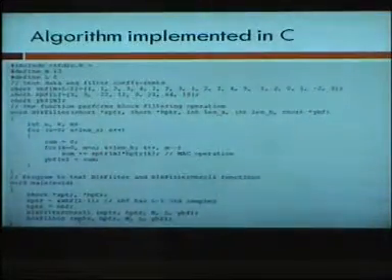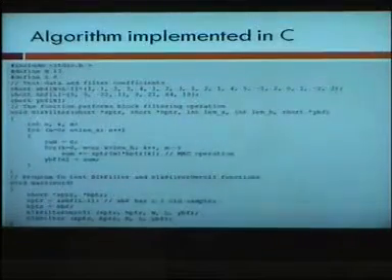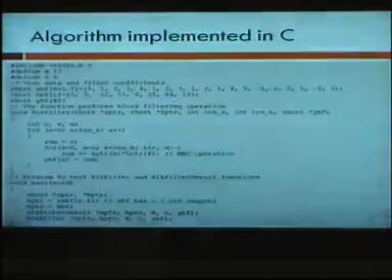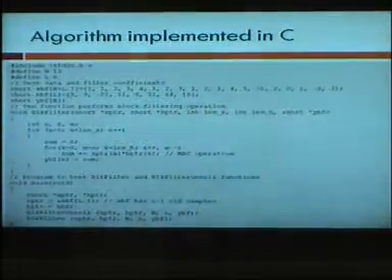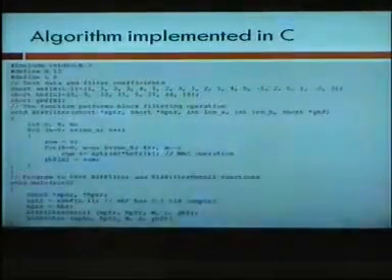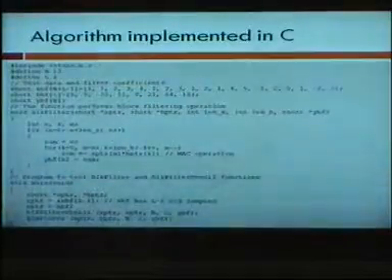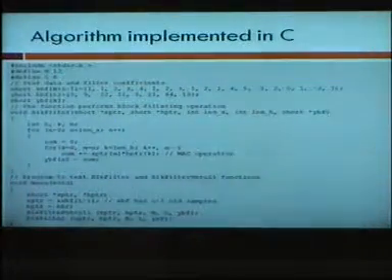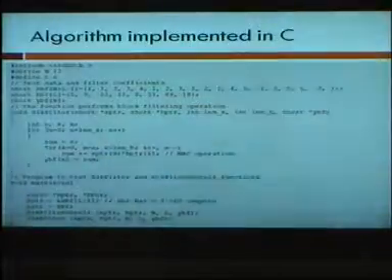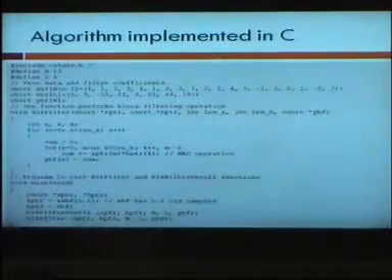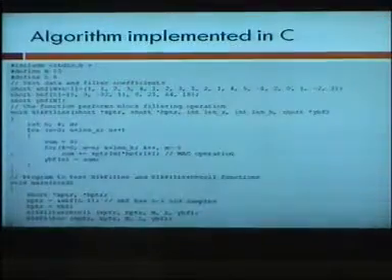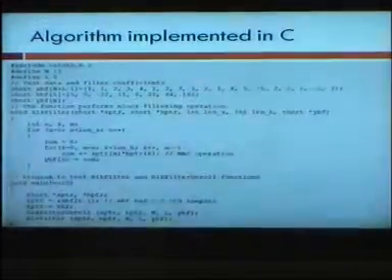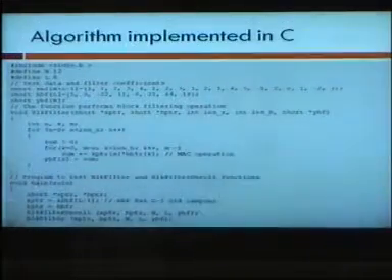And it is usually the case in signal processing: there's a for loop and another loop, another loop, another loop, because in software the processor can only do one multiplication and addition, number one. Number two, your mind thinks in that way. Your mind will never think in terms of parallelism, because this is what you have learned. It's a sequential way of doing things. So this is the best you can do in software, and this is the main limitation: though Pentium will be very fast, very smart, it'll just be stuck doing all this, and almost all programmable processors will have this inherent limitation.